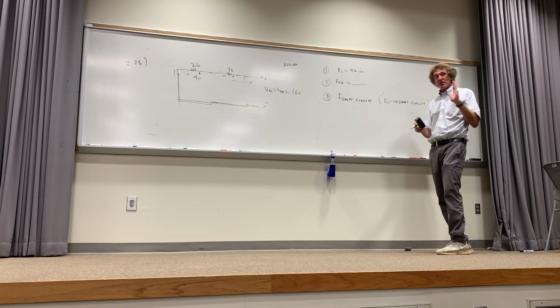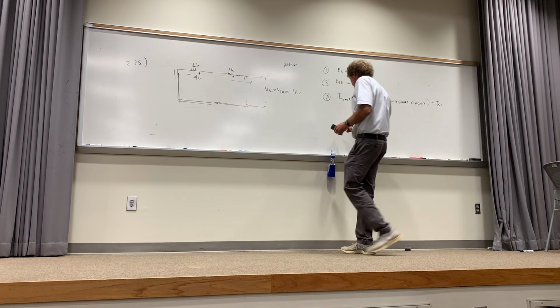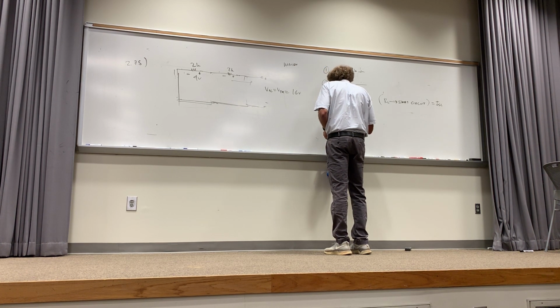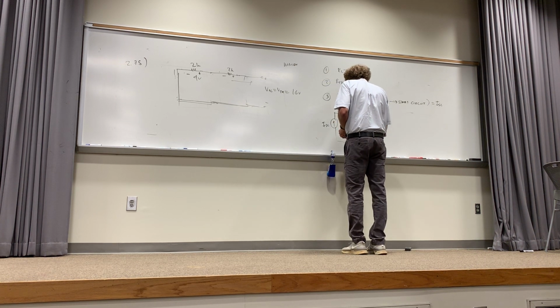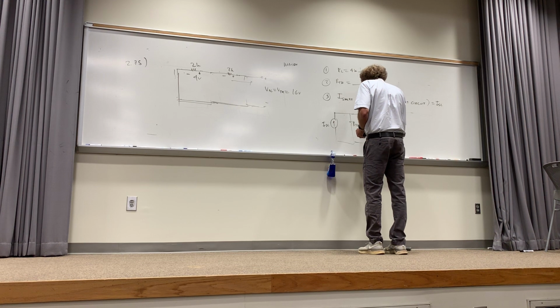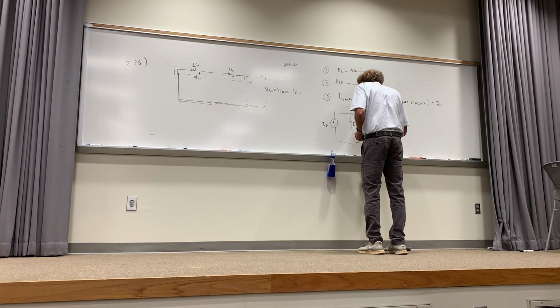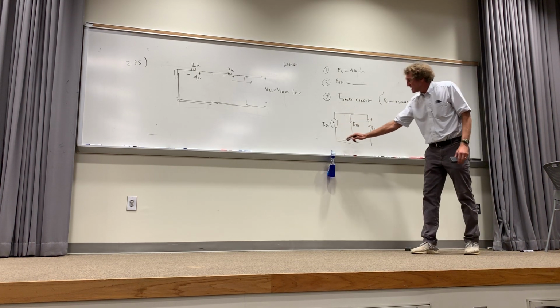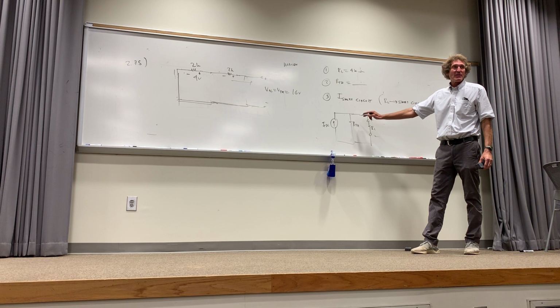Then our circuit looks like this. We put I short circuit there, and we put the resistance R Thevenin in parallel, and then we put our load on. Then you go ahead and replace our load right there. Do y'all see this? Now here's a tip. You see what this really is? That's just a source transform of a Thevenin circuit. That's all it is. Y'all see that?